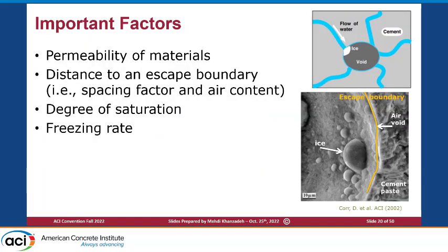These are important factors in our durability design. One is the permeability of the system. The other is basically your spacing factor, your failure, the degree of saturation, and freezing rate. The parameters we're going to focus on here, since we are discussing the mass transport and application of these techniques in the mass transport, are degree of saturation, how we can get help to understand the impact from spacing factor as well as the permeability.